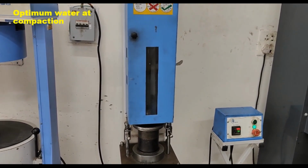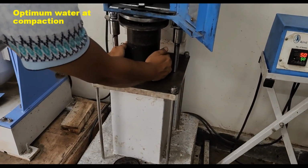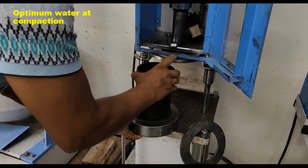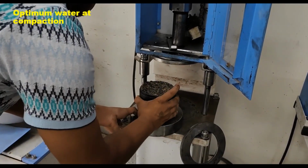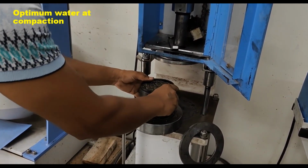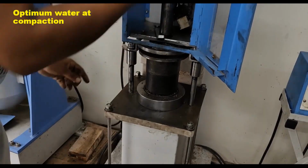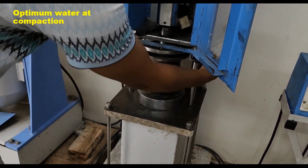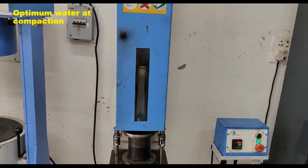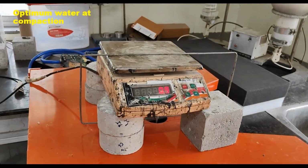After 50 blows, remove the collar and base plate. Reverse the mold and reassemble. Apply 50 blows on the second face also. And after that, you cure the specimen in the mold for 1 day at room temperature and then extrude.